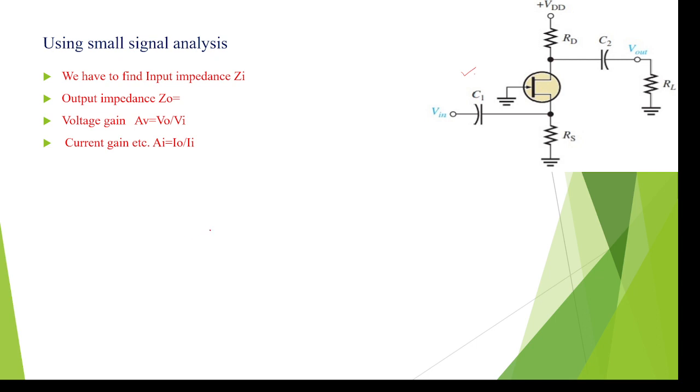I am drawing here. First we need to draw the equivalent current source for the transistor, which is in between the input and output side. So I am writing here gm multiplied with VGS, that is IDS. Why? Because gm means transconductance: output current divided by input voltage VGS, multiplied with VGS. VGS cancels, only IDS is there. So that is the current equivalent.